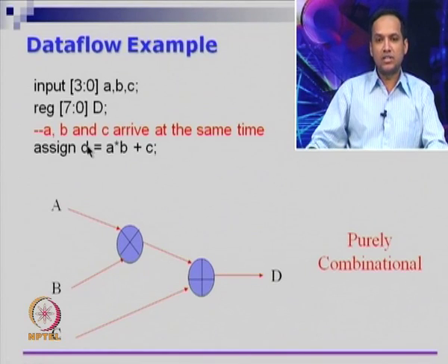So, D is actually an 8-bit number, and if you wrote something like this, so forget the declarations, if we had anything like assign D equals A times B plus C, then the implication is we have A, B, C which are the inputs and D is the output, and A times B. So there are tools called synthesis tools, which can look at this line of code, understand that star means multiplication, and actually throw in a multiplier there, and also understand that plus means an addition and throw in an adder there. So this plus is adder and this cross is multiplier.